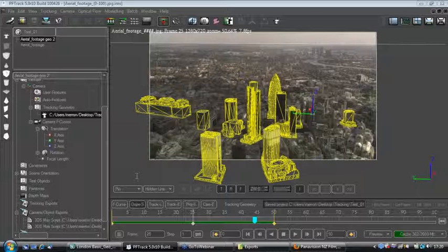How would you test your track in PF Track? I tend not to, because I don't really use the test objects in PF Track, in that I don't render out PF Track to make my movies in the end. So I'll bring it into Max and render out a test object on a plane with shadows. When you render without shadows as a test, stuff looks like it might be grounded, but when you render out of your 3D application with shadows, just do something quick, you don't have to have GI or anything stupid like that. If those shadows seem to be sliding around, you can guarantee that you've either got the scenery orientation incorrect or the tracking's off slightly. So just doing a test object, it might look good, but it might not be grounded where you would expect it.